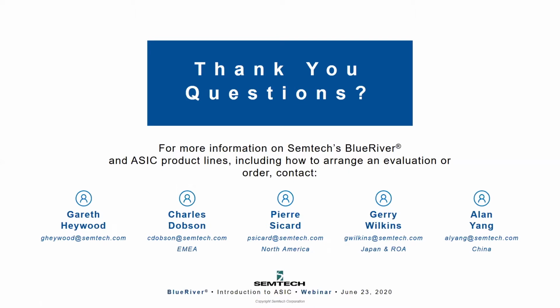All right, the next question: will native Ethernet enabled endpoints using BlueRiver ASIC be supported using power over Ethernet? Yes, because we rely on standard IEEE compliant 10 gig PHYs, it's your choice. You can use that with a PoE or PoE+ type solution. For example, we have reference designs which show how you would use PoE. Depending on what your endpoint is, the designer of that endpoint would have to determine what the power requirements are over PoE. But that's all fully supported, though it's not specifically part of the ASIC. It's more a system level design.